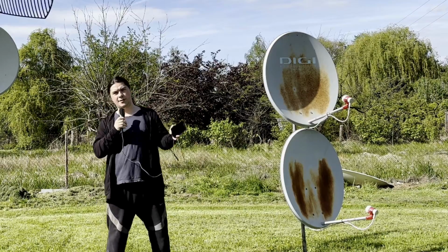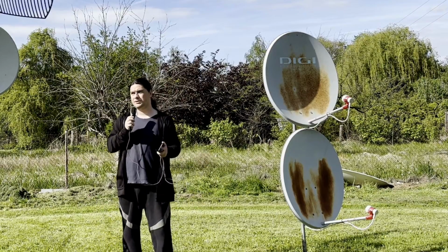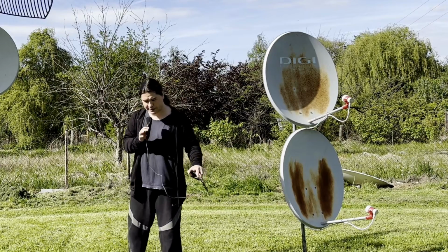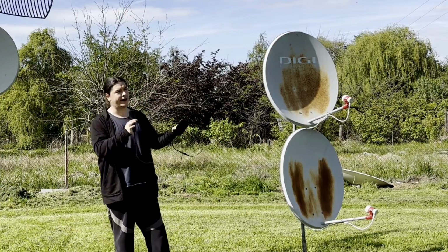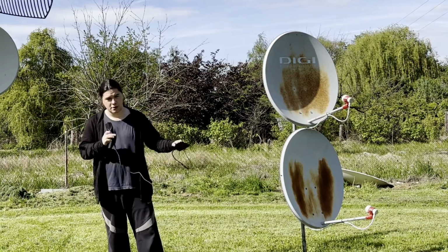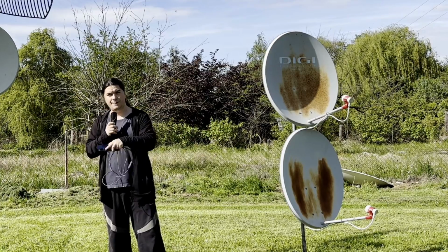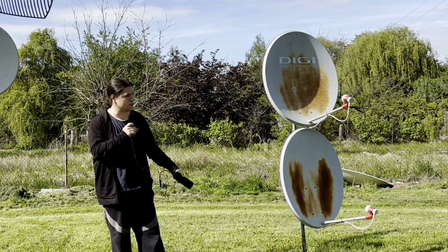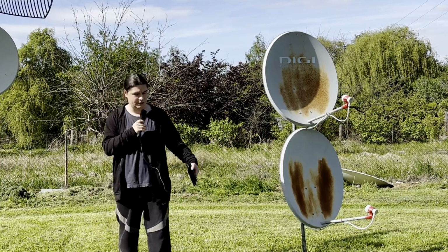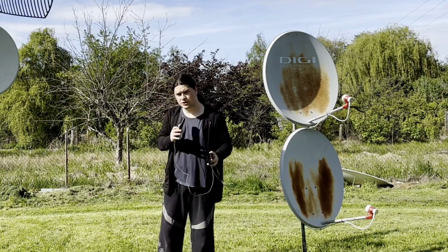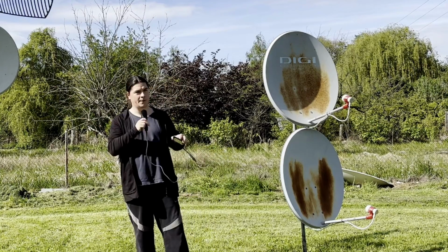A couple of things about using a power injector like that are important to keep in mind. Do not power an LNB, or any active antenna for that matter, without a proper RF load connected to its output. The bias T itself does not count, because the bias T only lets the RF pass through. You do want either a 50 ohm dummy load or at least the SDR connected, even though it's not connected to a computer.